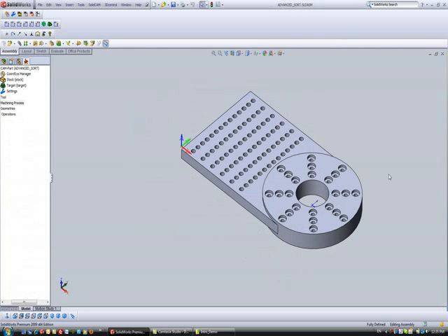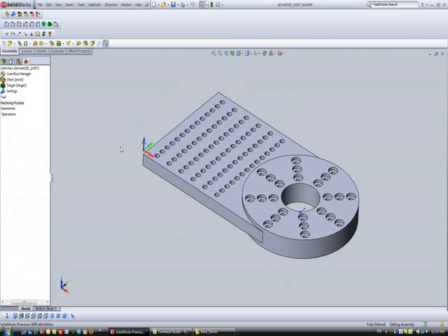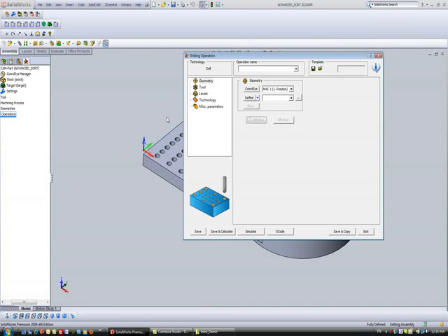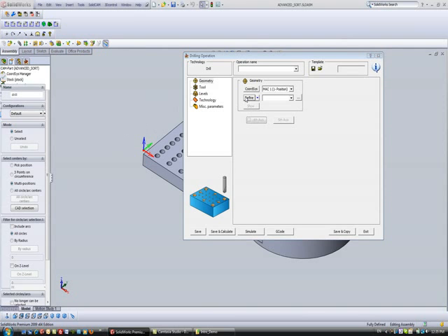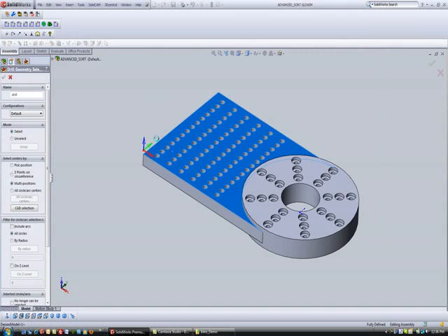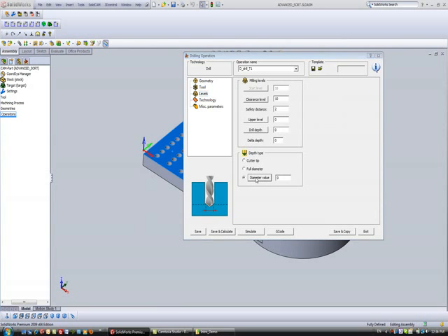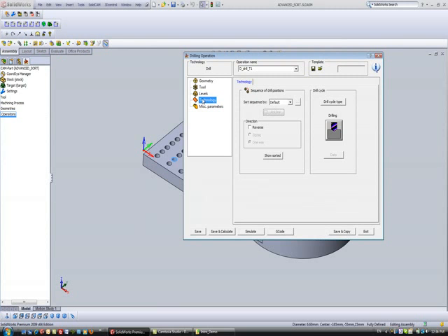Next, we'll take a quick look at our new drill sorting options. If we were to open up an operation over here, say drilling, and we'll choose our geometry as these holes over here. I'll go and choose my tool, say a 6mm spot drill, my levels according to this particular diameter over here. When I go into my technology area, we have here this sort sequence by default. By default means the exact same way the part was built. However, we have here a new option called Advanced.